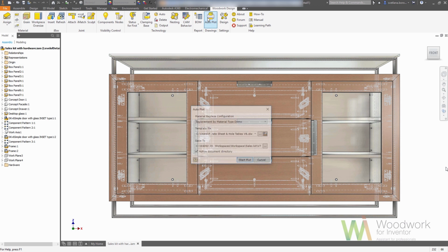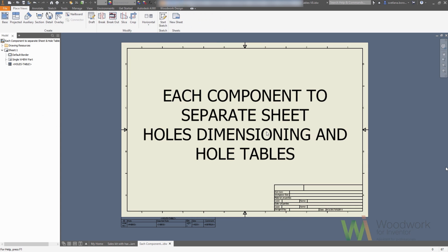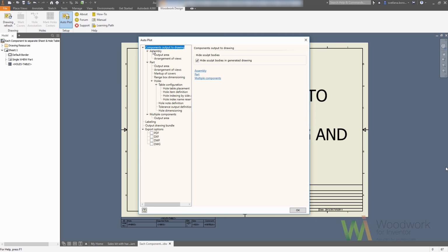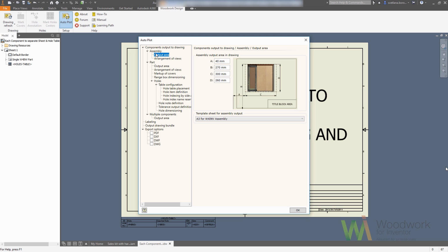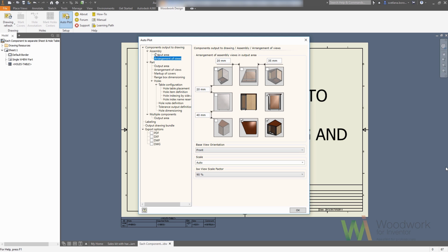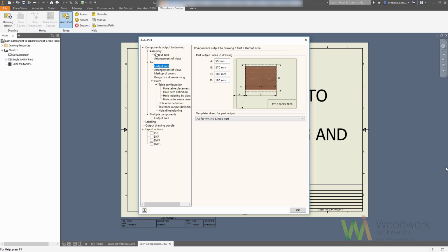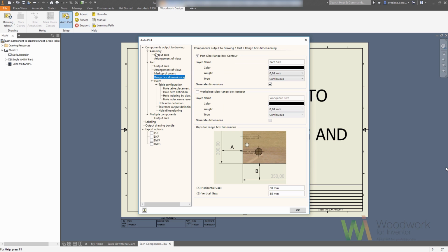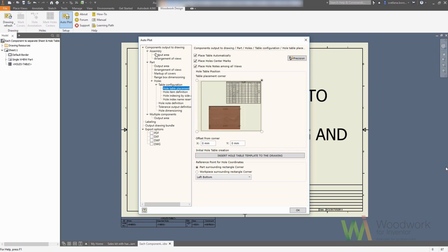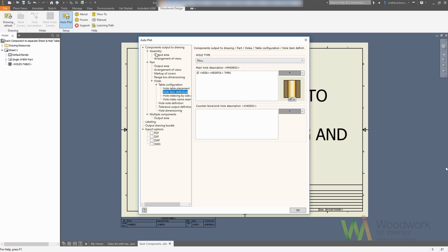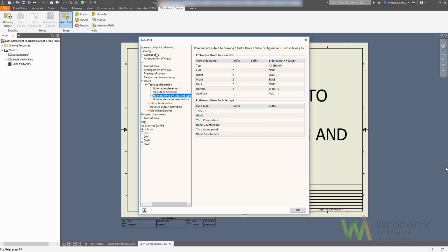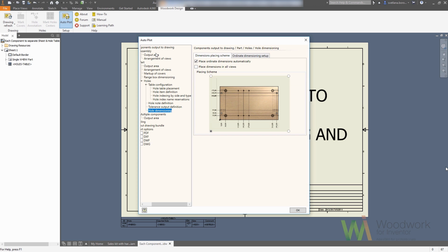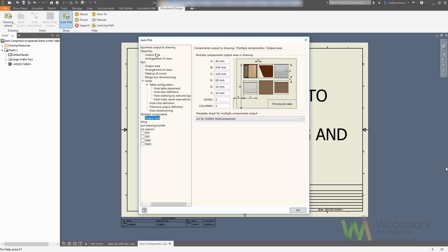Now we have an assembly. We are going to the auto plot, and we can briefly go through the template to see what you can change. In different aspects of the drawing, you can change different things. For instance, the projections, the output area size, the colors for the lines, the thickness of the lines, whether you want a hole table, a hole chart or not, whether you want some hole indicators and in what way they should be assigned, the tolerances, the coordinates of the holes.